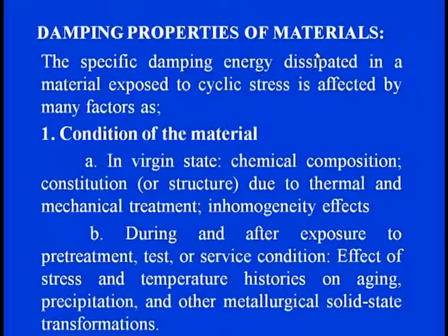When we are absorbing such heat, the aging effect and other metallurgical solid state transformations related to the microstructure of this material clearly feature a change, a clear transformation of the microstructure, the grain boundaries and even the grain sizes. Accordingly, the damping properties evaluated for the material itself are not the same as things move with time.